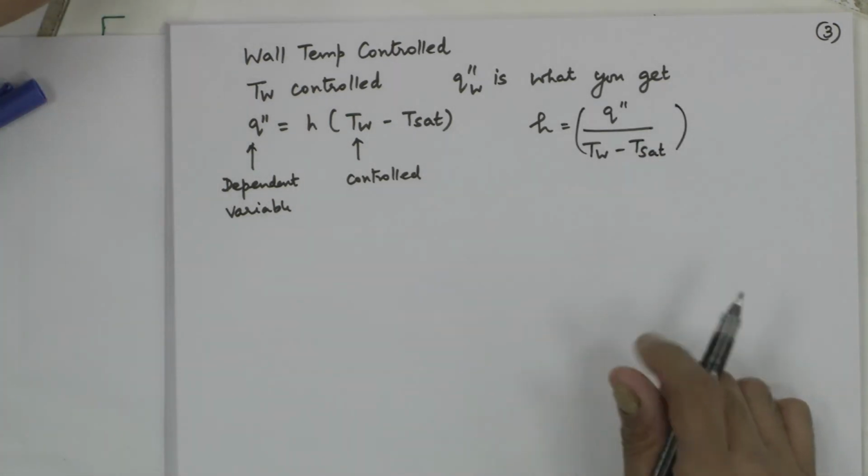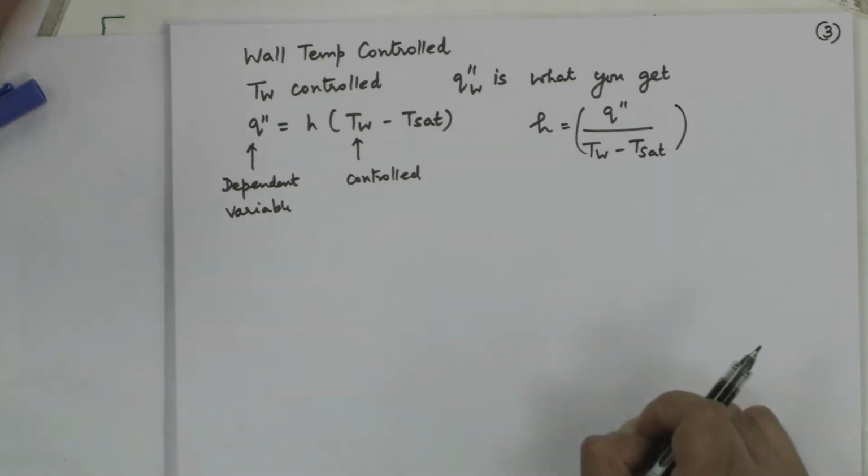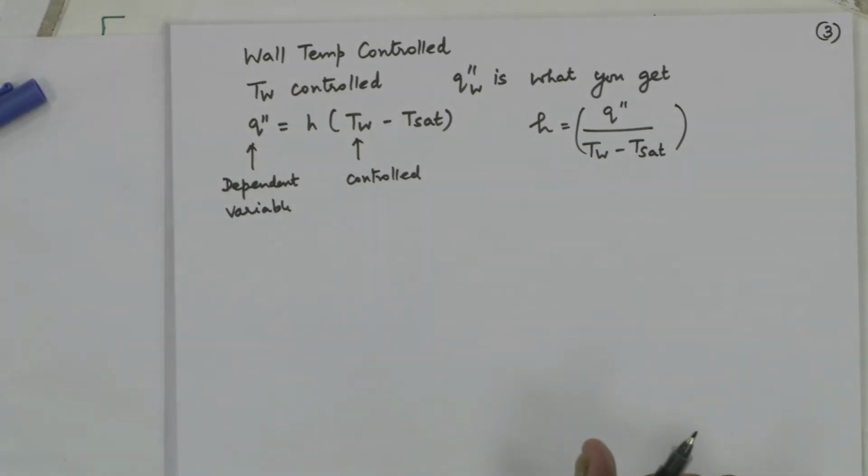We do the same thought experiment, with wall temperature being progressively increased. It is a little bit difficult to control, because you have to progressively increase the wall temperature. How is wall temperature controlled? It is controlled by having condensation or boiling happening on the other side, where you want the phenomenon of nucleation to occur. For example, if I have to give heat for boiling to occur, the temperature of the surface should be greater than the saturation temperature, which means some liquid must be there on the other side supplying heat such that the temperature of the wall remains constant.